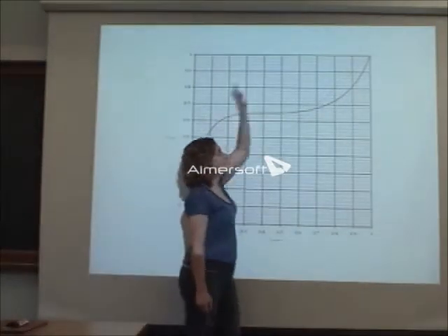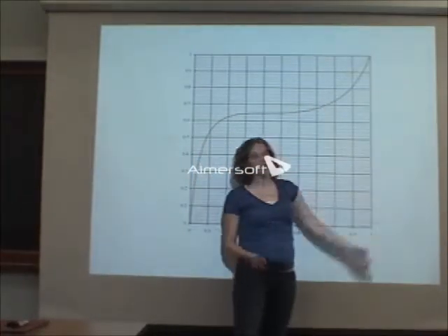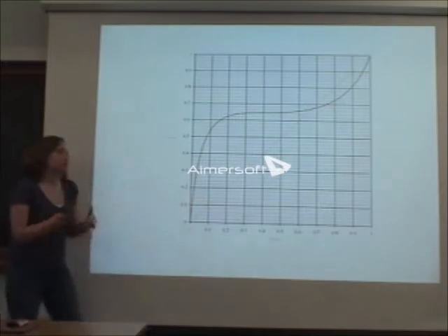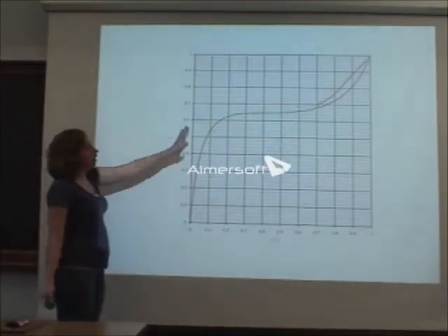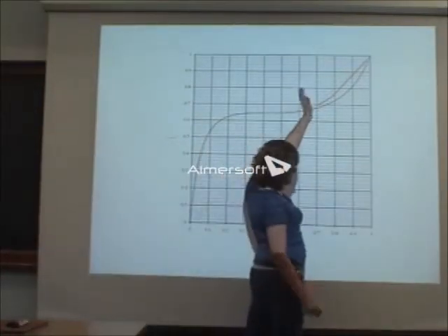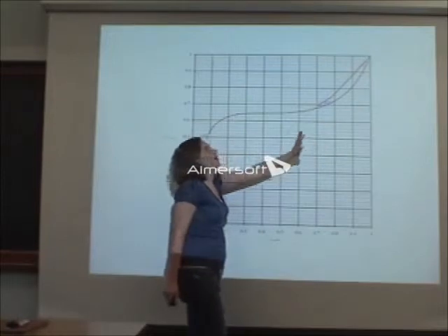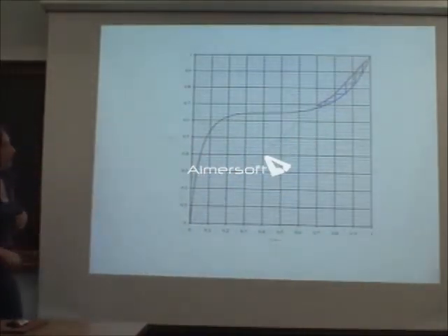Switch over, we're now on this map. We still have that same output coming out of our other column, right? Just because we're changing its pressure doesn't mean we're changing its overall composition. So we're going to draw some feed stages up in this corner. And we're going to follow the same formula as we did for the last column and draw ourselves some stages and put it up there.